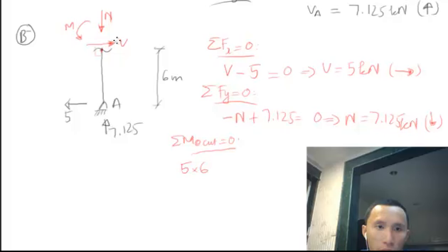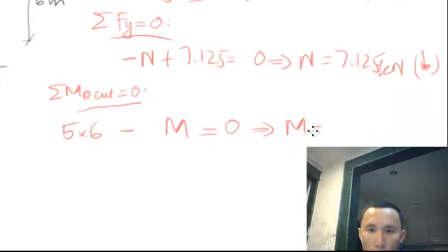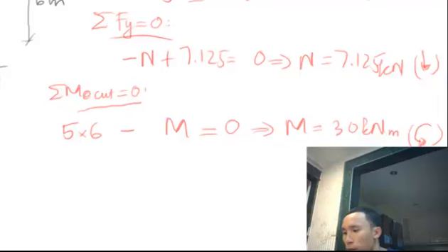That's cancelled, that's cancelled, that's cancelled. So only this one. Now moment. If moment goes anti-clockwise, so negative moment equal to 0. Therefore, moment equal to 30 kilonewton meter. And it's positive again, so our first assumption is correct, this way. That's it for B negative section.